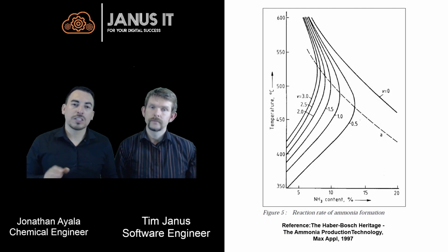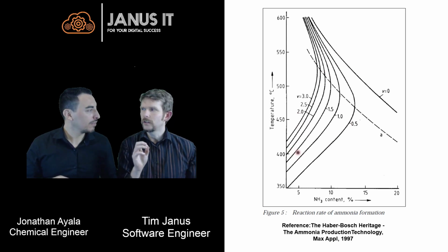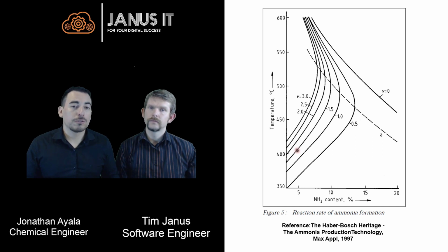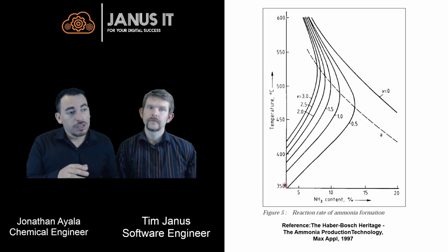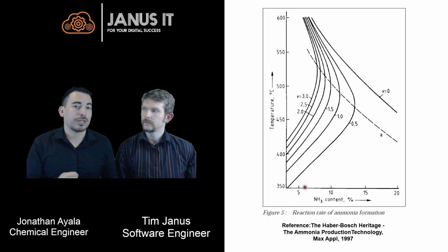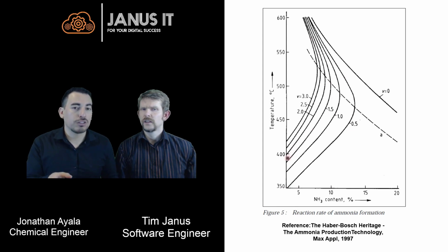Now, if we direct our attention to this graph, we're looking at the reaction rate of ammonia formation. Wait a moment, it seems there's a lot going on in this graph. Maybe you can introduce us to the axes first. Yeah, of course. This graph is a crucial tool for chemical engineers. It visualizes the complex relationship between the temperature of the reactor on the y-axis, the concentration of ammonia on the x-axis, and reaction rate. So the curves labeled with V are the iso rates. Each curve represents a constant reaction rate for the formation of ammonia.